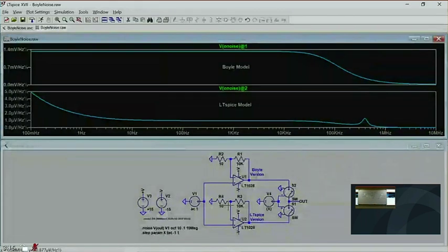What's up with that? Well, that's because the input differential stage of the LT1028 is so quiet that when it amplifies the signal, the subsequent stages add noise, and this amplified noise from the input hasn't swamped the noise from every other stage. And you will see the noise from those intermediate stages when the feedback loop goes open circuit because of loss of gain bandwidth.